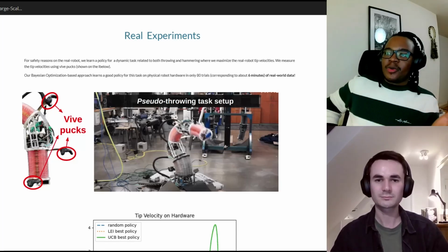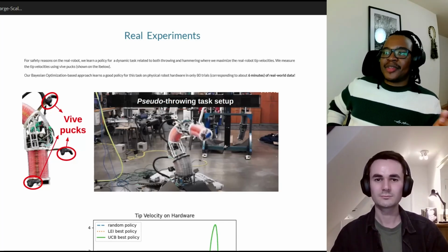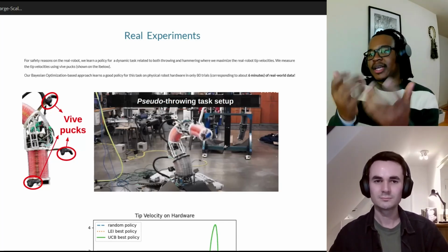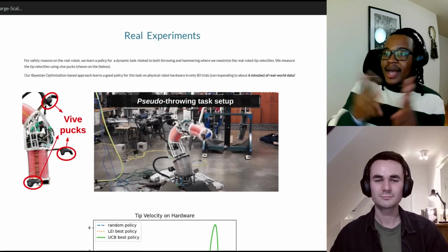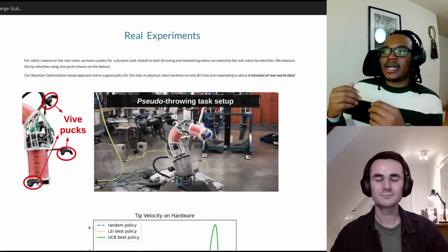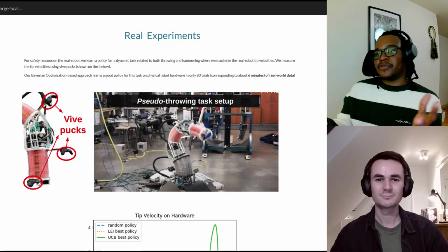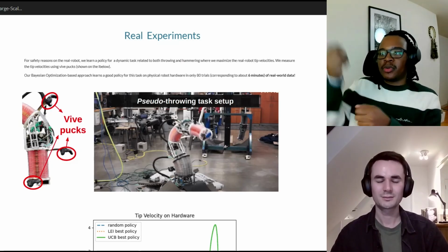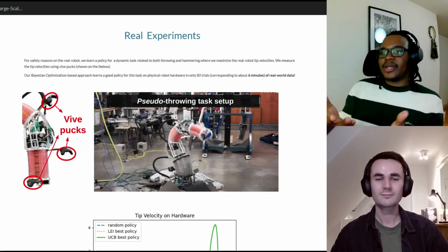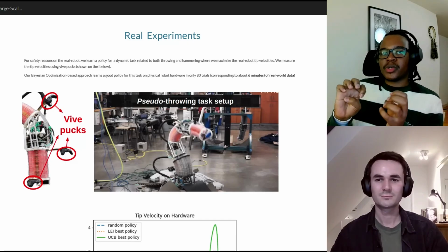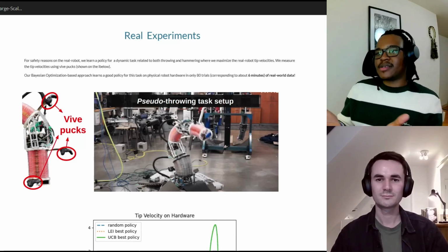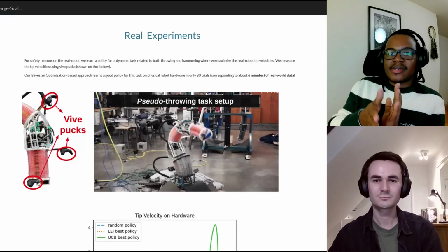100%. And then also it depends on what it's made of. Some of them will be made with plastic, some of them will be made with, I don't know, some kind of steel rings and things like this. Some of them will be pneumatically driven and they'll still work like an elephant's trunk. And some of them will be cable driven, which is, there are some motors that spin and then pull different sections around to actuate the robot. And all of these will have different dynamics, right? Hence coming up with some standardized model that's going to work for all of them is extremely challenging.